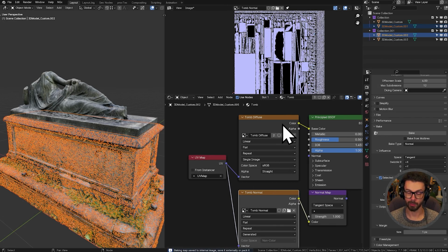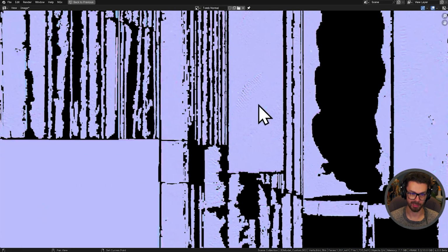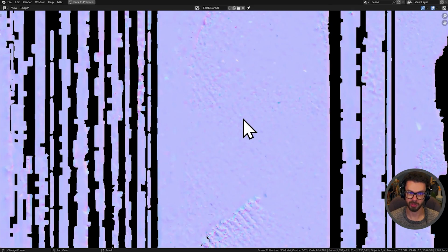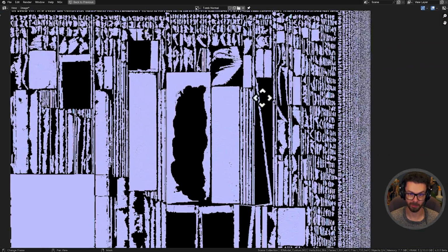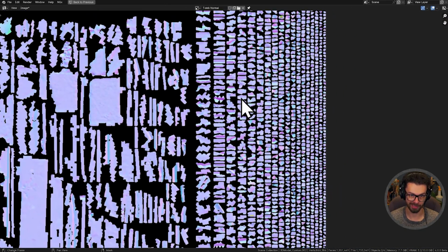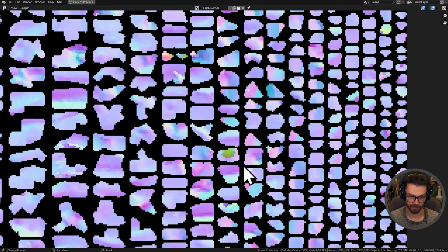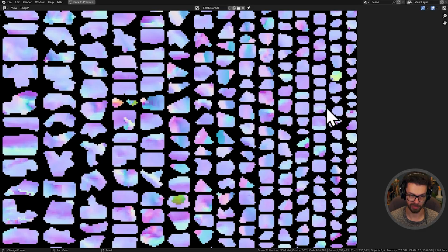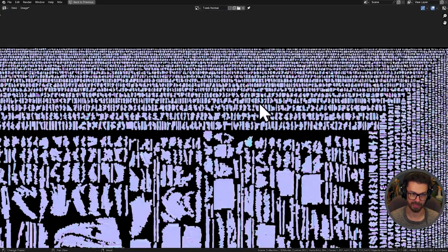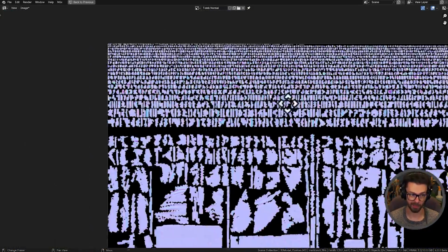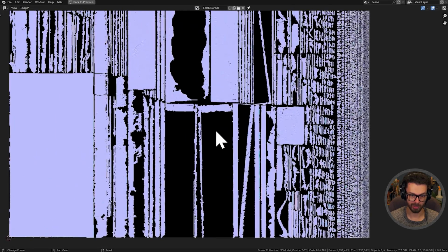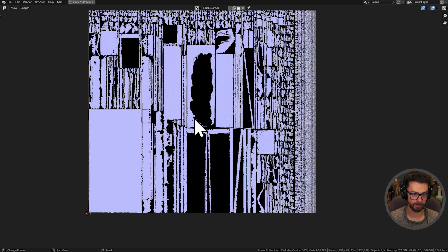It's always good when you're doing a normal map just to do a little bit of a sense check. So this is the approximate color that you want. If you see anything which is bright yellow or bright red, it's quite likely that you have some failure points on there. So this is going to be an artifact. This is going to be an artifact, I would expect anyway. In general, looks like we don't have any large issues.